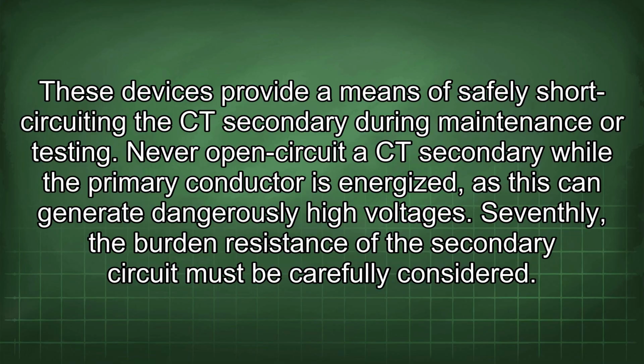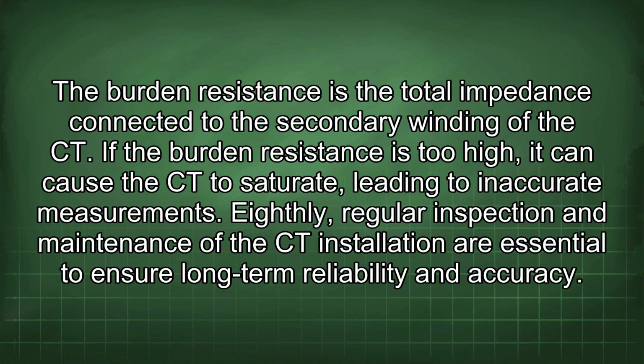Seventhly, the burden resistance of the secondary circuit must be carefully considered. The burden resistance is the total impedance connected to the secondary winding of the CT. If the burden resistance is too high, it can cause the CT to saturate, leading to inaccurate measurements.